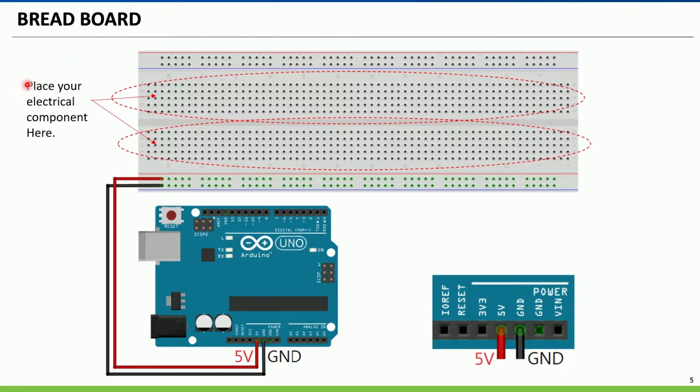And this one, the breadboard again, is the place for your components, in the center with the vertical line. These five dots are connected to each other. And for example, you place the power supply 5 volts or ground here. In Arduino, a power supply of 3.3 volts and 5 volts is available, and also 3 grounds, this ground and this ground.